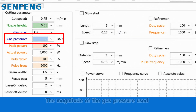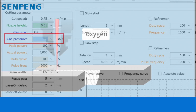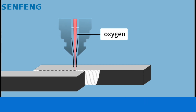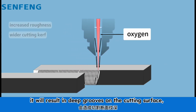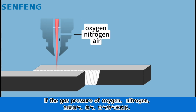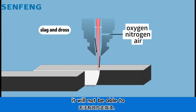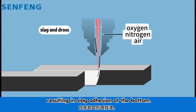Gas pressure. The magnitude of the gas pressure used during the machine's cutting process. If the gas pressure of oxygen is too high, it will result in deep grooves on the cutting surface, increased roughness, and a wider cutting curve. If the gas pressure of oxygen, nitrogen, or air is too low, it will not be able to effectively blow away the molten slag, resulting in slag adhesion at the bottom.